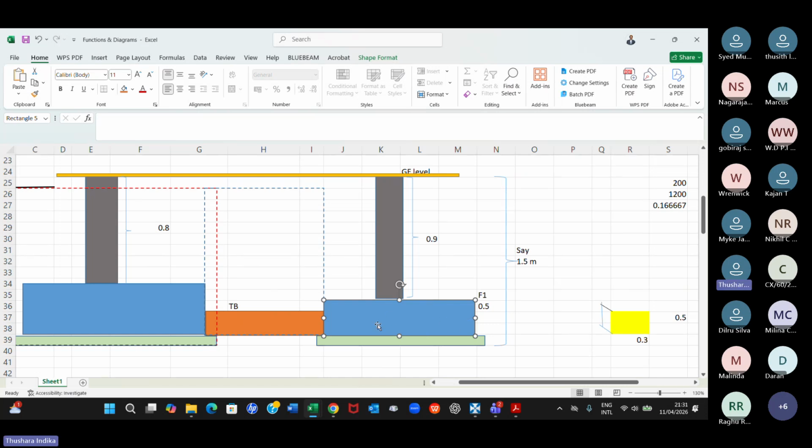So that is one area that will be painted with bituminous. How do you get that area? You get the footings and get the wall area, the perimeter into the thickness or the height. And that is basically your formwork, similar to the formwork area for the footing.